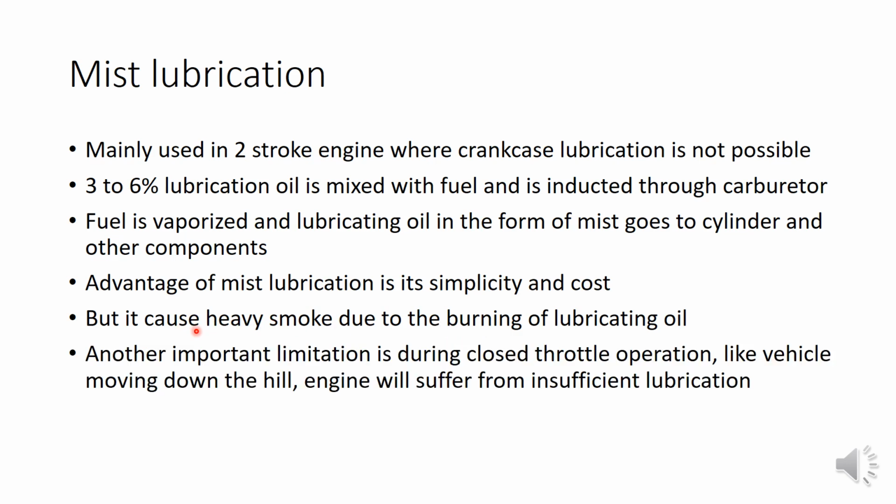And another main disadvantage is, suppose we are moving a vehicle down the hill, we will not press the accelerator pedal, which is known as a closed throttle operation. So fuel will not be entering into the cylinder in that case, because our throttle is fully closed, very little fuel will be entering. So the lubrication oil also will be very little since it is mixed with the fuel. In that case, the engine will suffer from insufficient lubrication. So this is an important limitation of this type of lubrication.